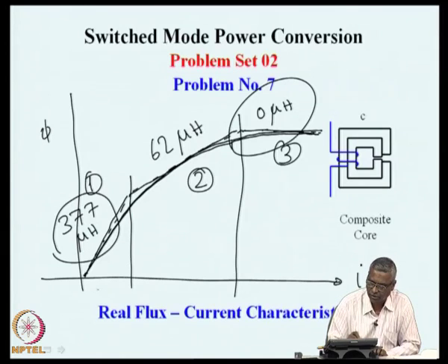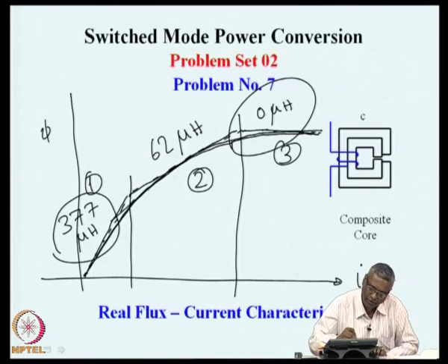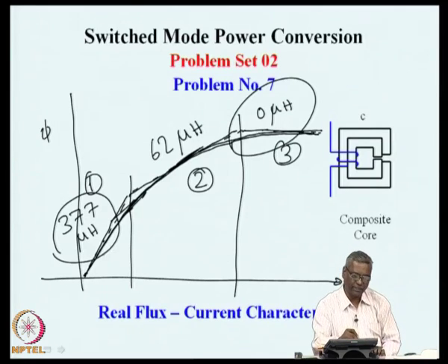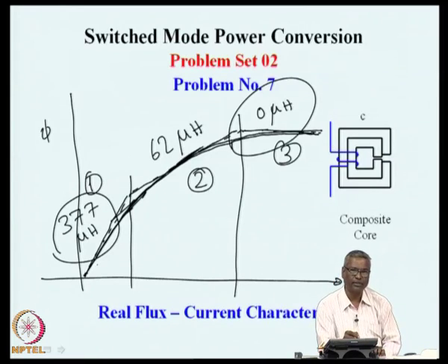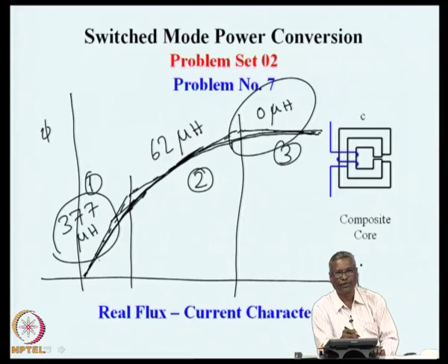In this case, as you go to higher current, you can see that the tangent of this line or the incremental inductance keeps changing as the current is increasing, and the incremental inductance becomes smaller at higher currents and larger at lower currents, and this is a very important positive feature of a nonlinear inductor, which can be utilized in many applications in order to have nearly constant ripple, whether the unit is at light load or at rated load.